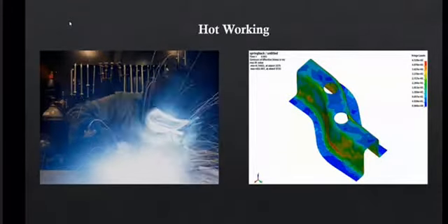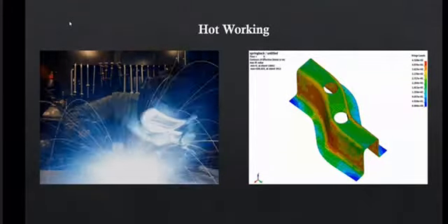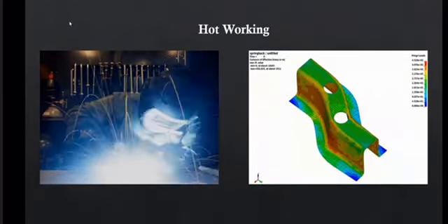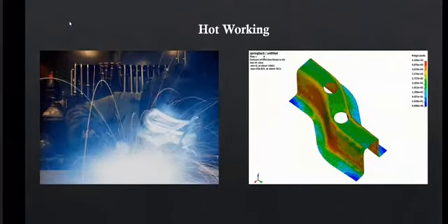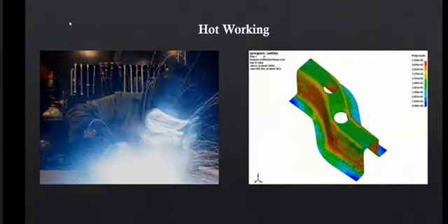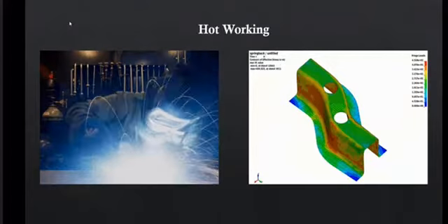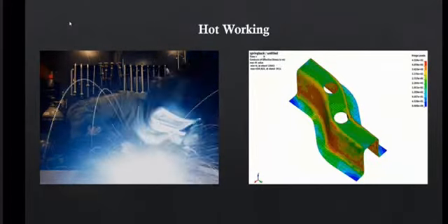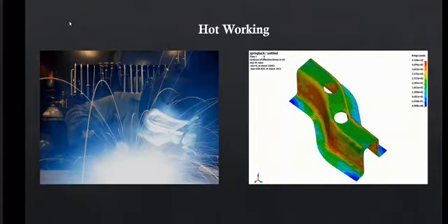Now we will discuss warm working. Because plastic deformation properties are normally enhanced by increasing workpiece temperature, forming operations are sometimes performed at temperatures somewhat above room temperature but below the recrystallization temperature. The term warm working is applied to this second temperature range.